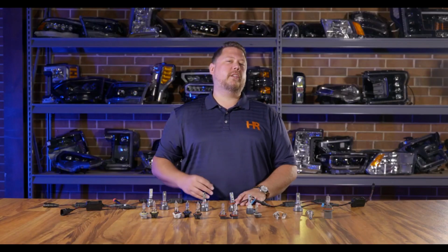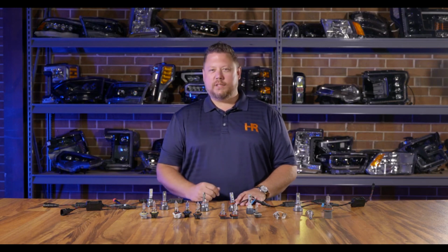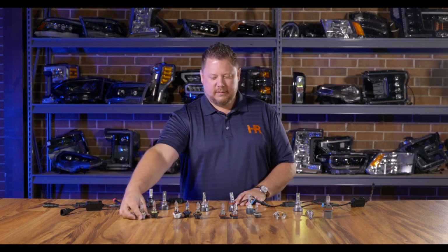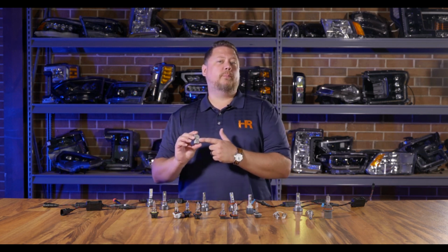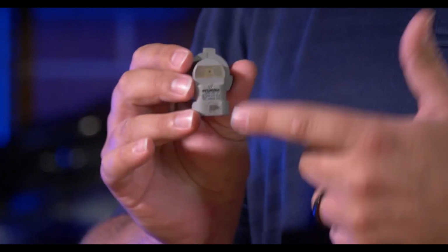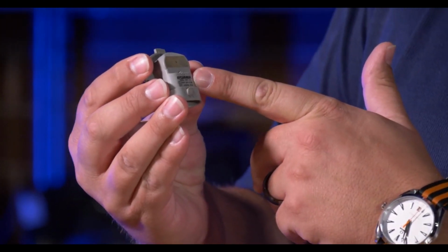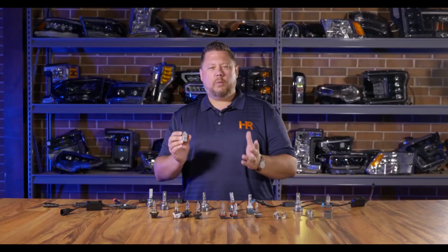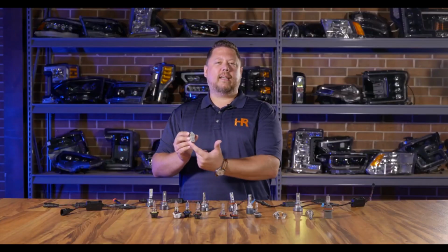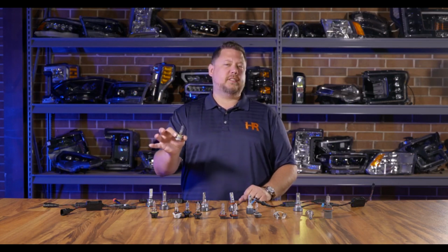If you want to figure out what you have now so you can get the right product for an upgrade, you have a few different ways of doing it. The easiest thing is to take your vehicle apart, pull out the bulb, and on the bottom or somewhere on the bulb is going to be the name of the bulb or the part number. This one, for example, says Sylvania 9006 HB4U. Don't worry about the U. You can either get a 9006 or an HB4. Both parts will fit the same light bulb.